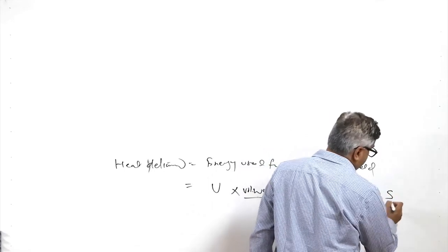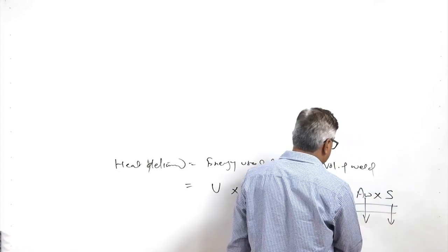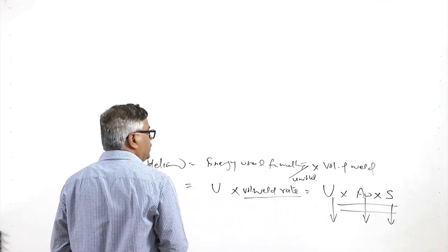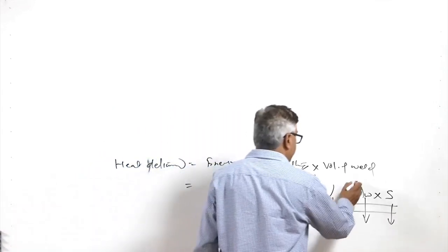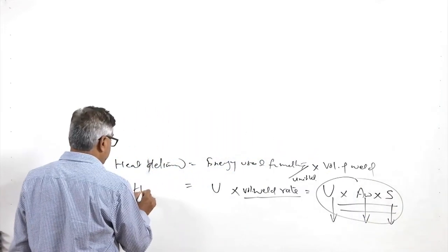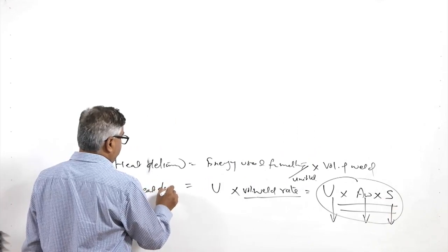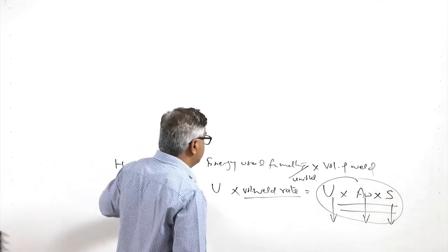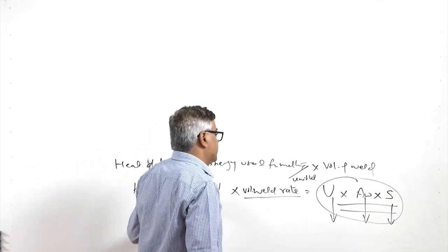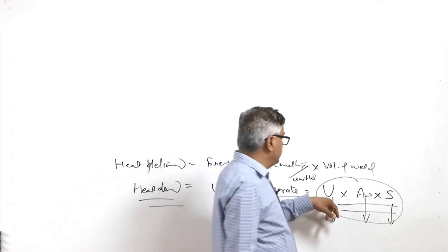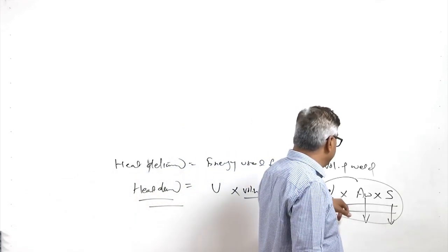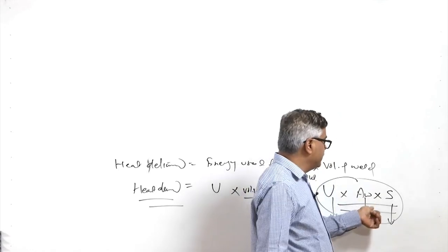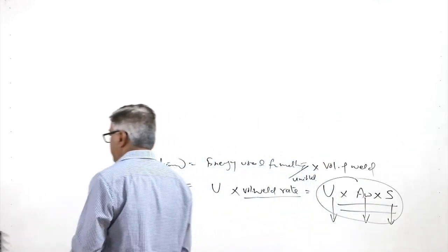So, the speed of the welding, the cross sectional area of the weld, and the amount of heat required for melting the unit volume of the metal will give us how the heat delivered is being utilized. If we are aware of the heat being delivered for the melting purpose during the welding, then we need the heat required for melting the unit volume of the metal, the cross sectional area of the weld, and the welding speed.